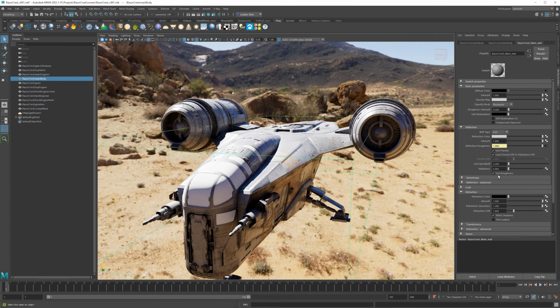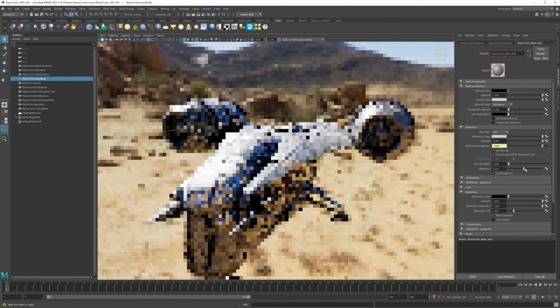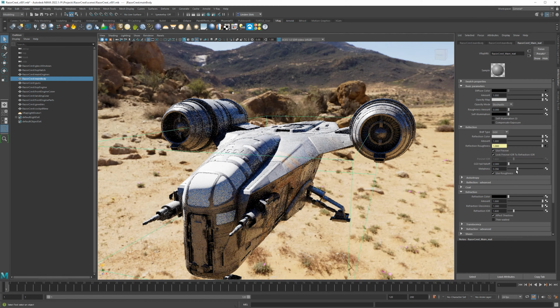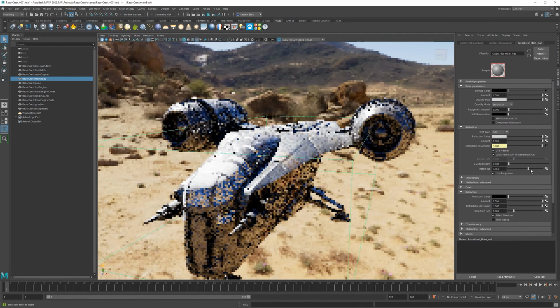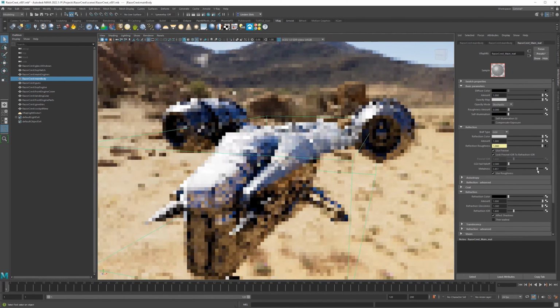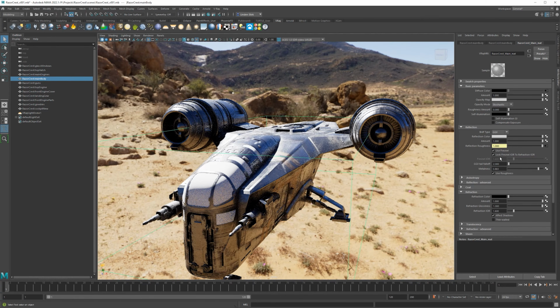Metalness basically means, is the object metal or is it not metal? And it's really not that difficult, but there's a lot of things that go wrong when you start doing bad things with metalness. Part of the reason is you have a slider. So you can start sliding up your metalness and say, oh yeah, this is 25% metal or 30% metal, or 80% metal. And that's wrong. That's not PBR compliant.